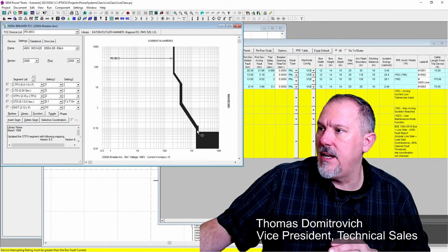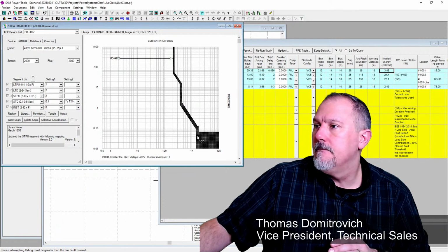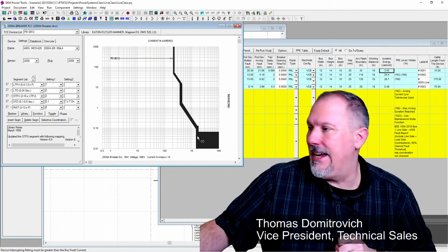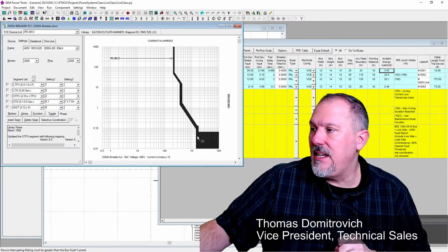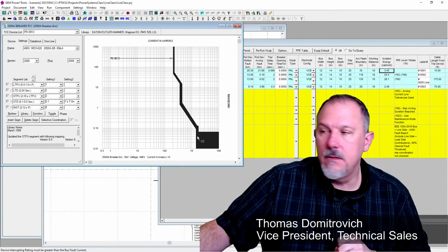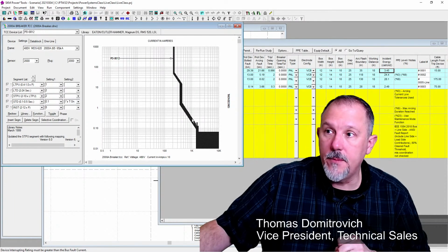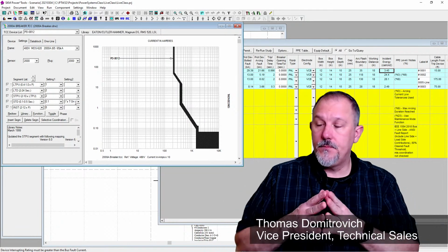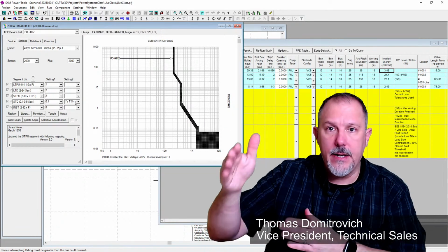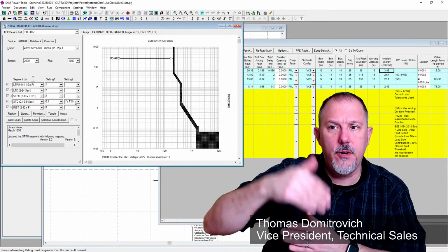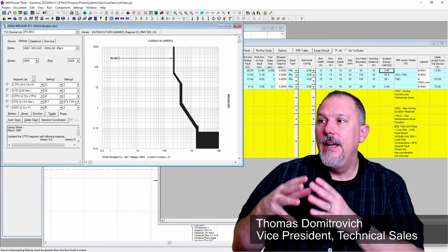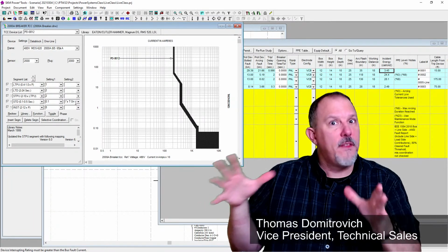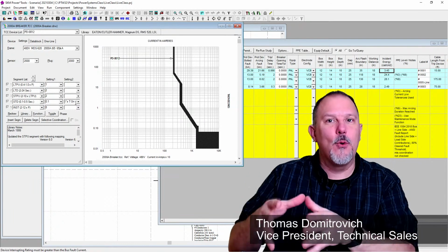Now I went to 6.9. So right there, I could take this as high as around 16,000 amps with this type of trip curve, and I've got a nice little delay for any inrush currents going on downstream, and I'm all the time at 3.45 calories.